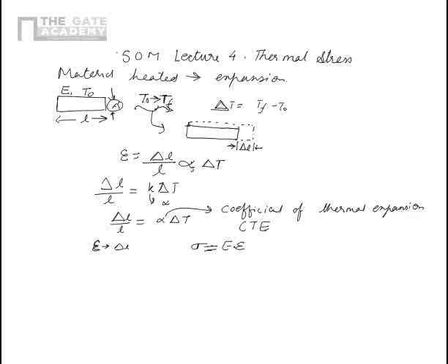That internal resistance is the cause of stress. In case of thermal expansion, there is no load applied, there is no resistance to any load. If we cut any cross section, we will see no force because there is no applied force. So there cannot be any reaction, because if there is a reaction inside, then it's an unbalanced force and the object should actually be moving, but it is not the case.